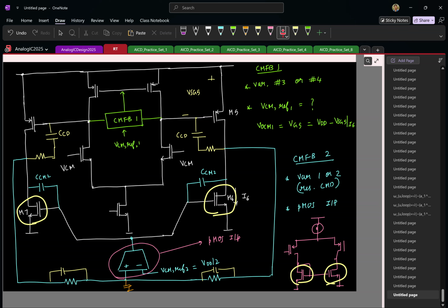And again, this will be your final design project, designing a 2-stage differential Miller OTA, right? You can reuse an OTA that you already designed. I'm sure you already designed the first single stage OTA for your first project, that you can obviously use and make a 2-stage OTA, and even these OTAs you can use the same thing.